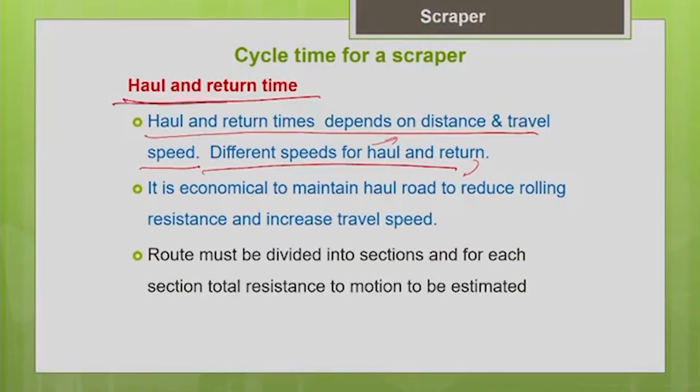You have to sprinkle the water and maintain the moisture content in the haul route, so that you can control the dust and improve the visibility at the site. All these things need to be done carefully to maintain the haul route. Whatever efforts you put into maintaining your haul route will help in reducing the cycle time of your machine. It will help in reducing the haul and return time. That way it will improve the productivity of your machine.